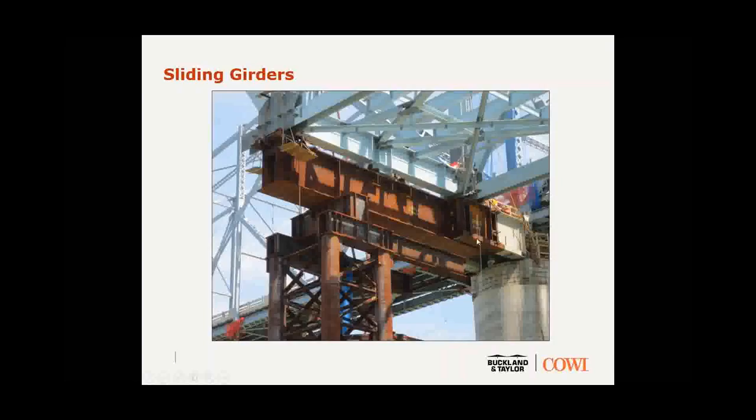The reason that was done was to leave the bearing portion, the final point of bearing of the truss on the pier, open to be part of the permanent structure. So once we slid it over, the bearing was in its final position, and this tuning fork was branched around it, after which it was removed and the pier cap completed.